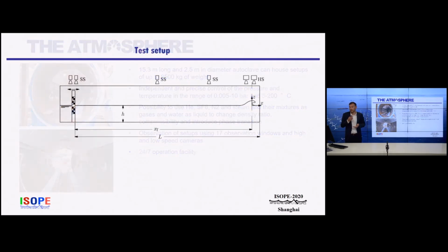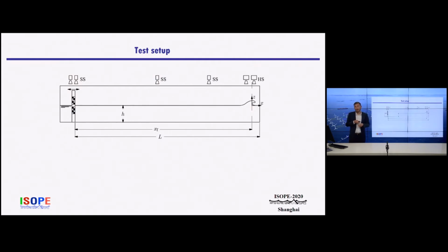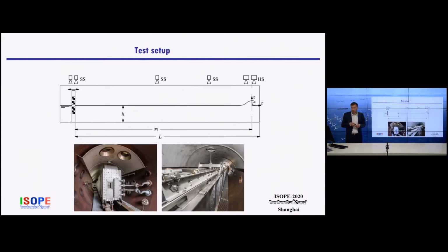involvement. All right, so coming to the test setup that we used in this study, it consists of a 12-meter long flume tank with a piston type wave maker, which is located at one end, and then on the other end we have a heavily instrumented impacting wall. We observed the flow using 4 low-speed cameras, which recorded at 200 hertz, and the impact is observed with 2 high-speed cameras, which record from 1 to 5 kilohertz. In these pictures, you can see this test setup, so the test tank.